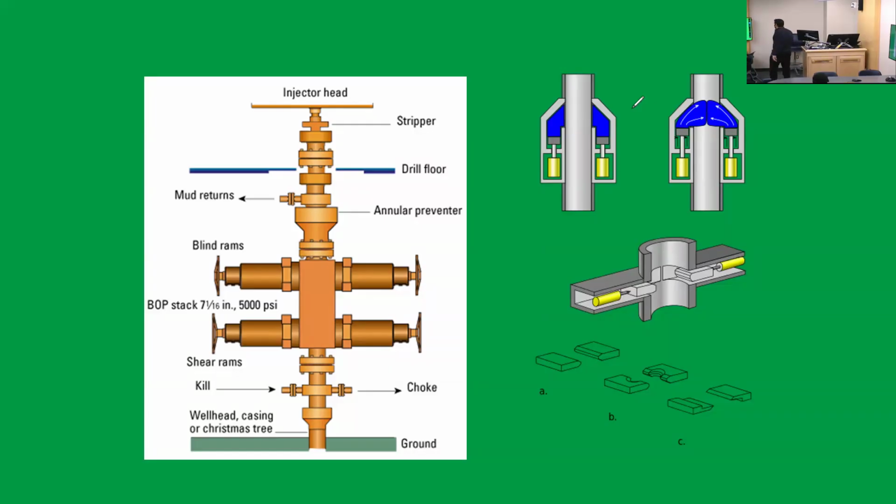So you're going to combine it with basically a shear. Or you need to cut everything, let it drop, and then close to basically seal safely. It's an emergency situation. You got to a point where you cannot save the drill string. You just cut it, let it drop, and then you close to shut in the well. Does the blind cut the pipe? No, it just covers. Now, blind shear, the modern day stuff, does this and this at the same time. So it cuts and closes.